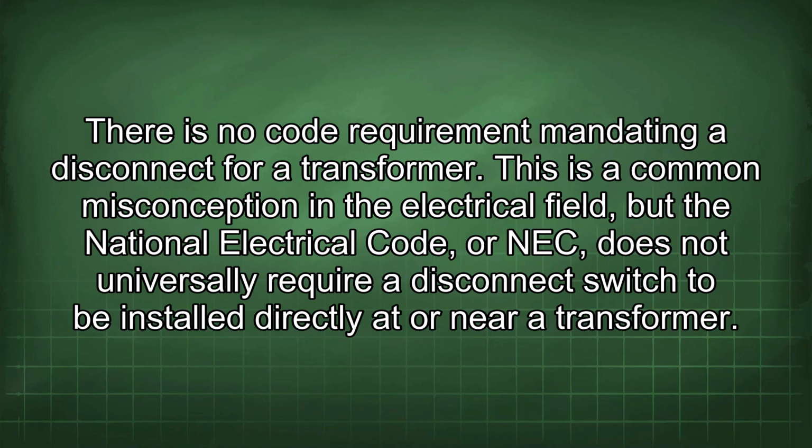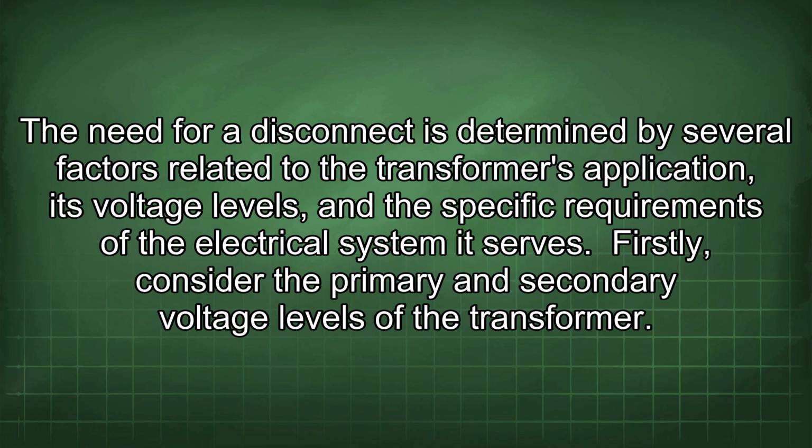There is no code requirement mandating a disconnect for a transformer. This is a common misconception in the electrical field, but the National Electrical Code, or NEC, does not universally require a disconnect switch to be installed directly at or near a transformer. The need for a disconnect is determined by several factors related to the transformer's application, its voltage levels, and the specific requirements of the electrical system it serves.